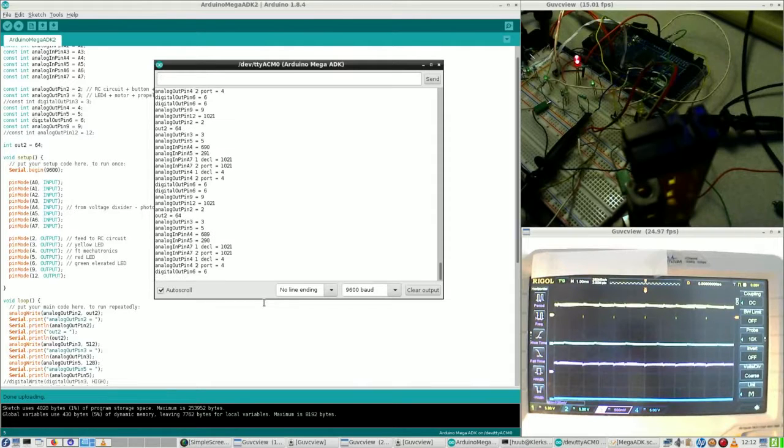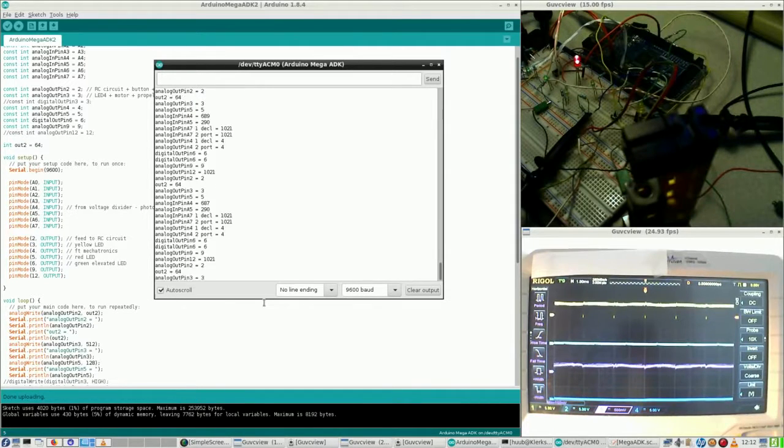But it also needs to be said that digital 1 is not 1 volt. Digital 1 means that the analog value is higher than a threshold value. So for instance, if you have 3 volts, then usually say 2 volts is a threshold, or it can be 1.8 volts being a threshold.